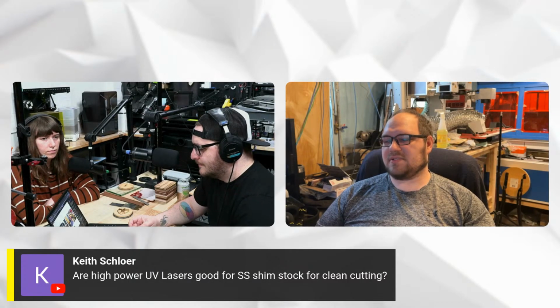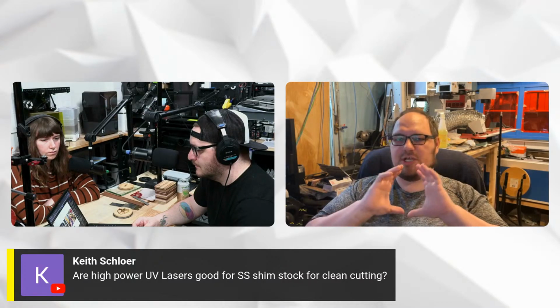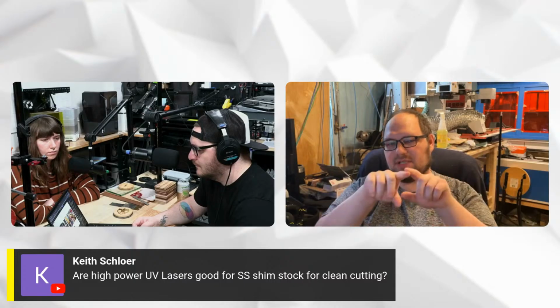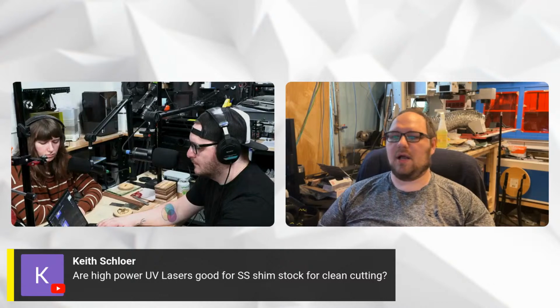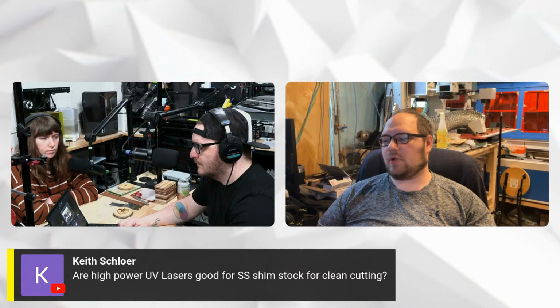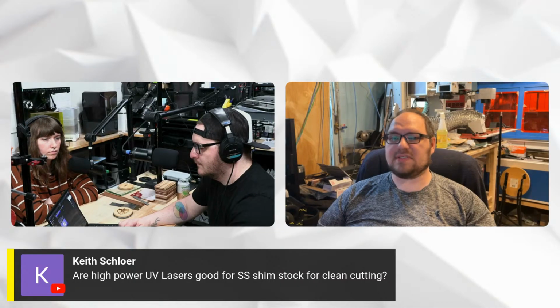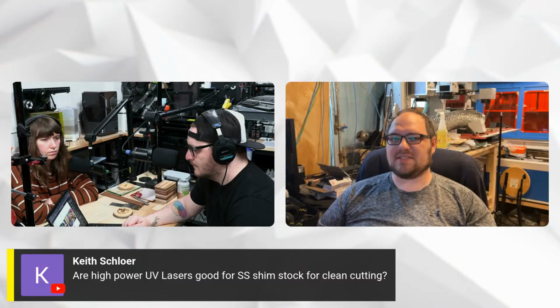Yeah, so galvo lasers are inherently problematic with cutting because they're always going to have a flared edge. Because if you think about like a movie projector, you're projecting a laser beam to cut something, and that means you're always going to have a tapered edge. So you're never going to have a truly flat edge when you're cutting with a galvo, and the thicker the material, the worse that's going to be. And also, your focal distance plays a part in that as well, because the closer the lens is, the more aggressive your angle is going to be.